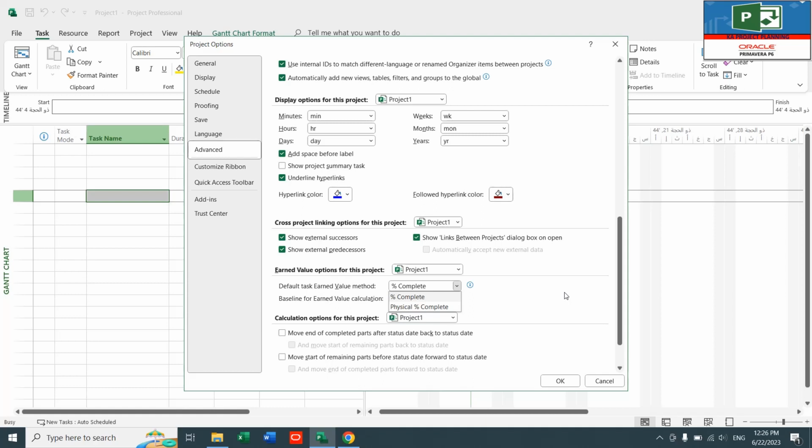The first one, for example, if I have 100 square meters of masonry work and I assign 10 days to do that work, and I have already done 5 days, that means my progress is already 50%. This is based on the percent completion method.